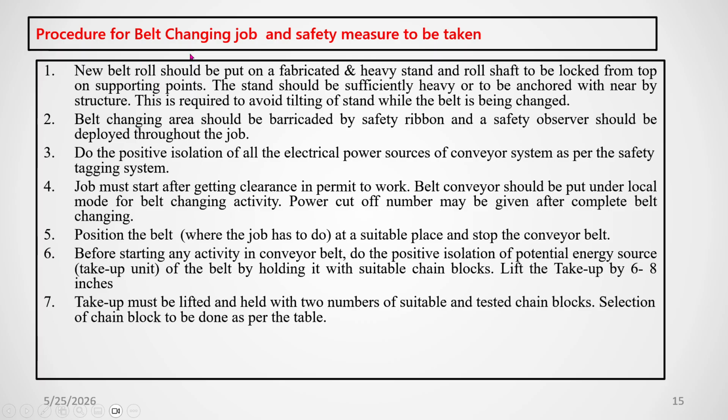Then the procedure for the belt changing job and the safety measures to be taken. These I have previously told you about for the repair. Now you have to replace it. So the new belt roll should be put on a fabricated and heavy stand, and the rolls have to be locked from the top on the supporting point. The stand should be sufficiently heavy so that it should not tilt, and be anchored with a nearby structure.